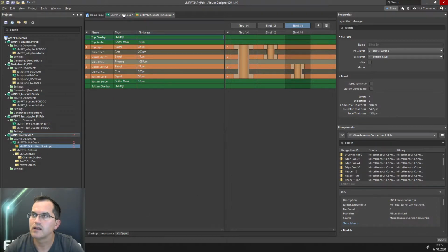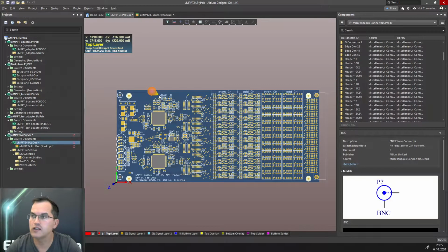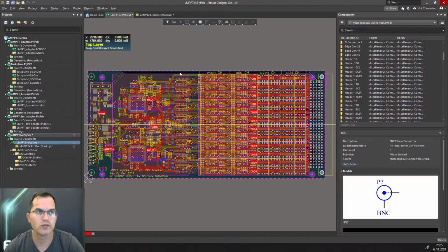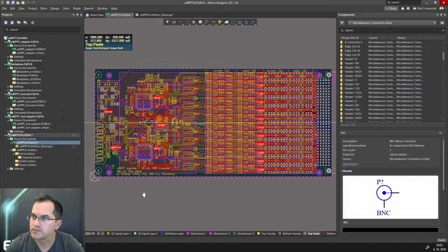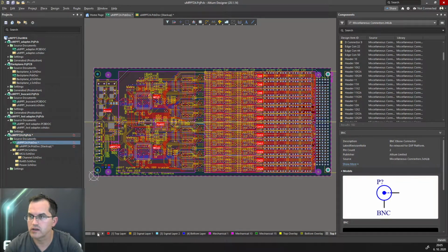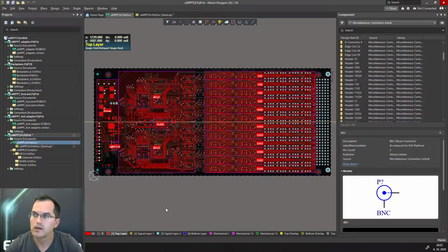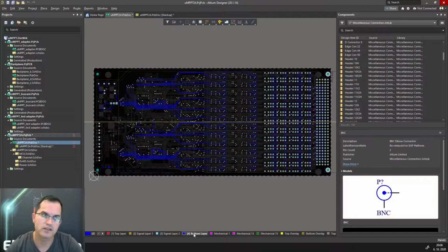All right, then what about the PCB itself? In Altium, you have several layers, and you have to know these layers. What are they for? So I can show here all the layers separately. So this is the top layer. It's called top layer. Sometimes it's also called the component side, because in old times on the top layer there were components, but now it's not the case anymore. Then the bottom layer, or the solder side. And here are the mid layers.